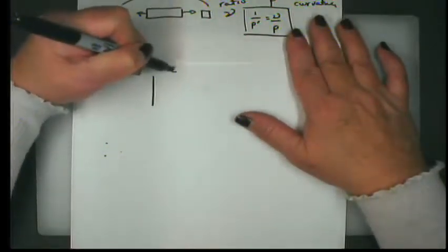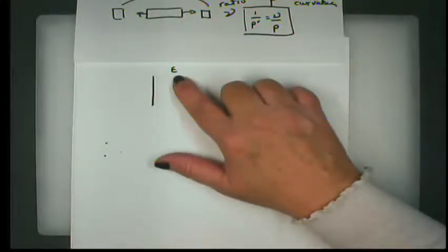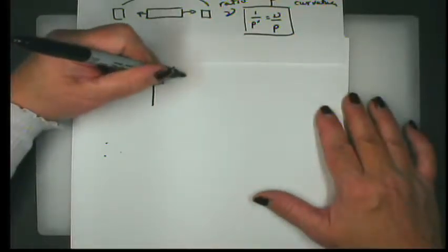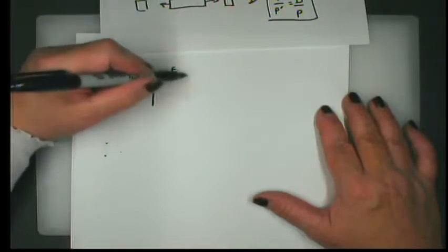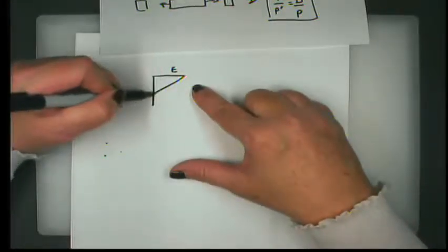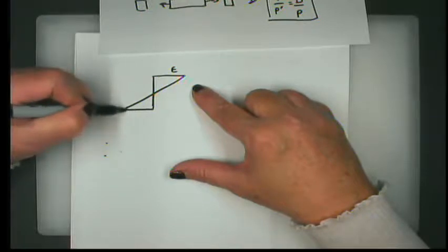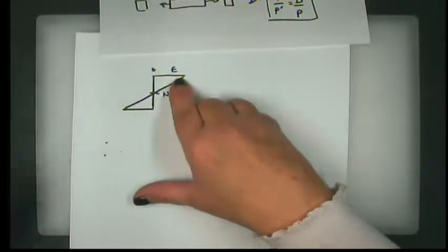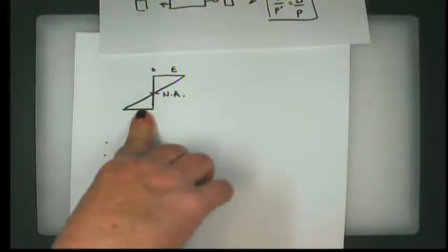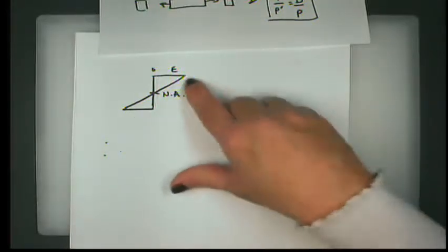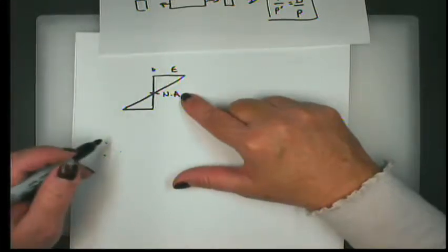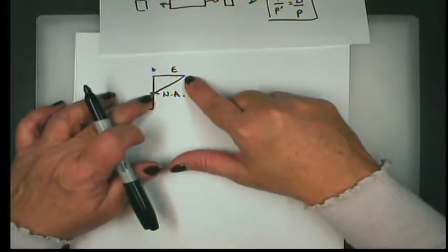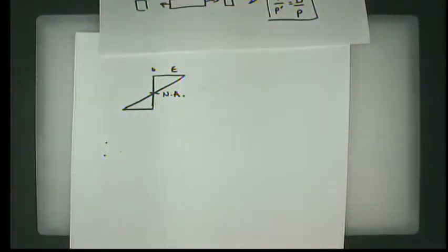So this leads us to the idea of epsilon, the unit dimensional change due to pure bending. It will be a maximum value at the top if we're in tension here. It will be a minimum value at the bottom, which will be compression, and it will be 0 at the neutral axis. The relationship for a homogeneous non-composite material is linear across the section. So you can determine what the stretch would be anywhere if you knew the location of the neutral axis and the maximum tension or compression.